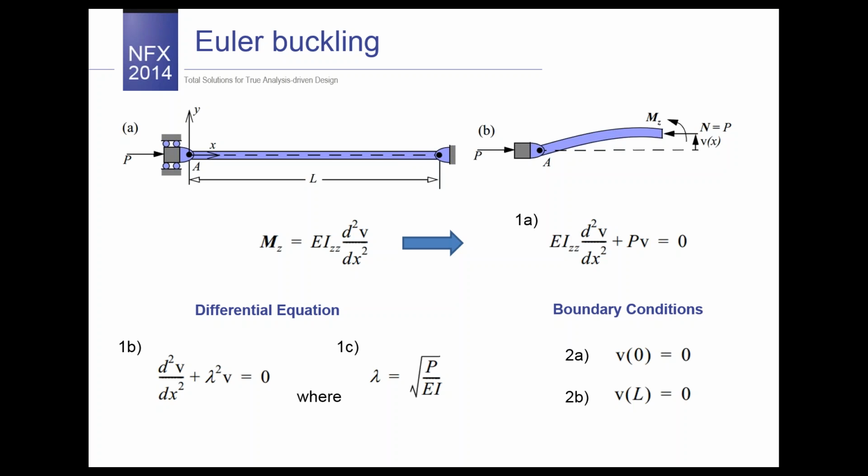As you see, this picture describes a simple boundary problem for the presented beam, and bending theory is used for the buckling description. Let me explain step by step what is needed to derive this buckling equation, which I hope you know. Let the bending deflection at any location x be given by V(x), a function V of x, which is shown in the figure.